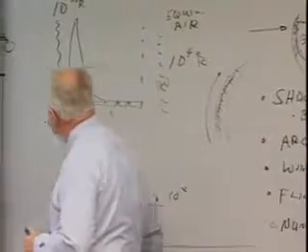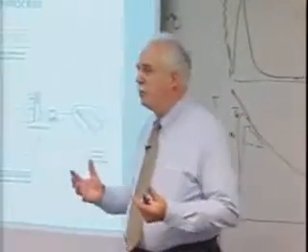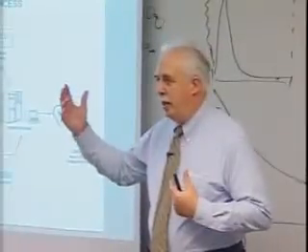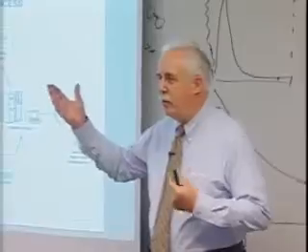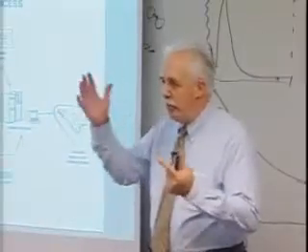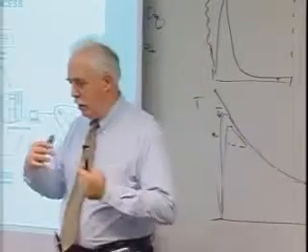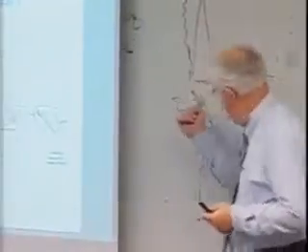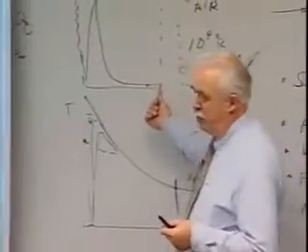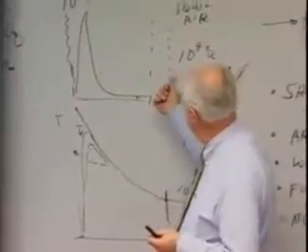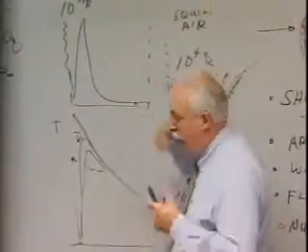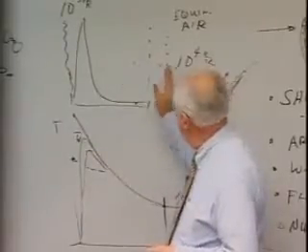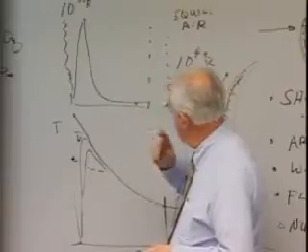Well, Professor Fay did a wonderful job in looking at a stagnation point on a sphere and saying, well, we've got limits. If we're at equilibrium, that is, the chemistry is fast enough that you're always at equilibrium all the way through the boundary layer, you get this amount of heating. And that amount of heating included not just the conduction, but the chemistry changes going from dissociated atoms and putting that energy back into translation and rotation in molecules. Or the other limit is completely out of equilibrium, where all you get is the translational energy.